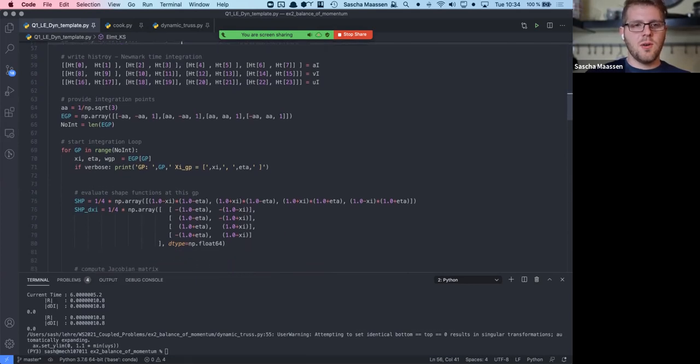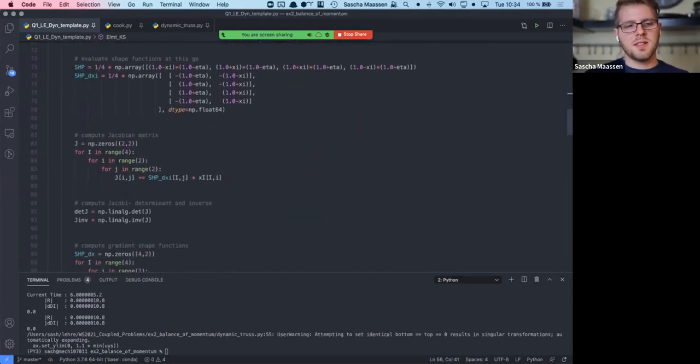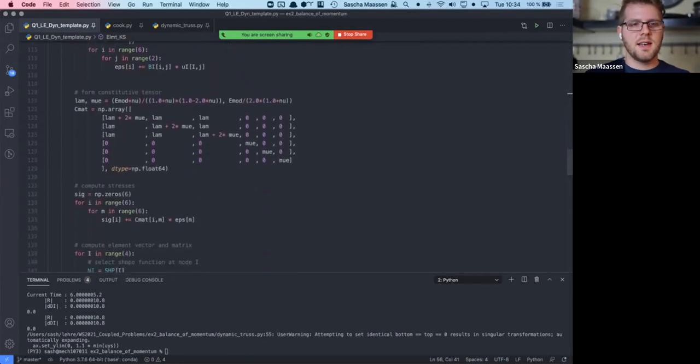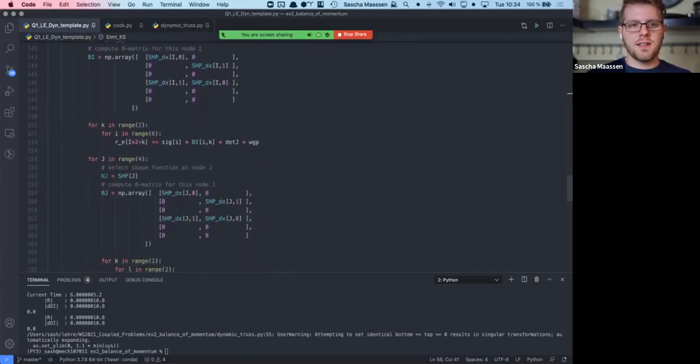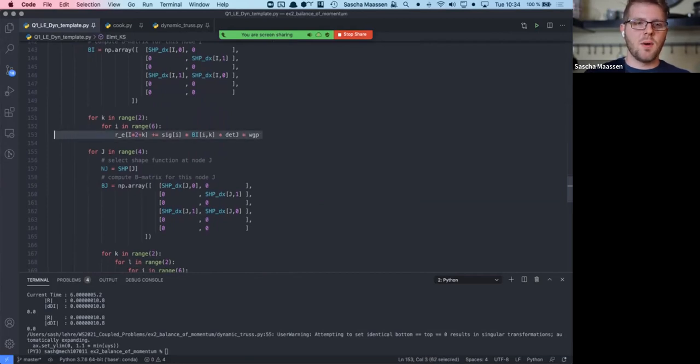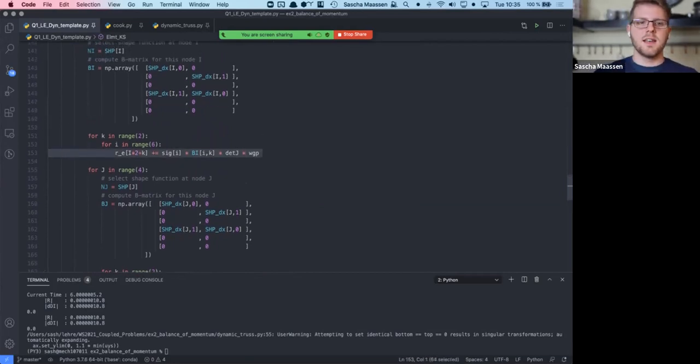Okay, so everything here, I guess, was discussed intensively last exercise. You have to extend a lot of things today, because if I look at line 153 here, this is the implementation of the right-hand side vector of this element with the part from the balance of momentum in the stationary case. This has to be extended now according to formula 10 from the sheet that we discussed before.